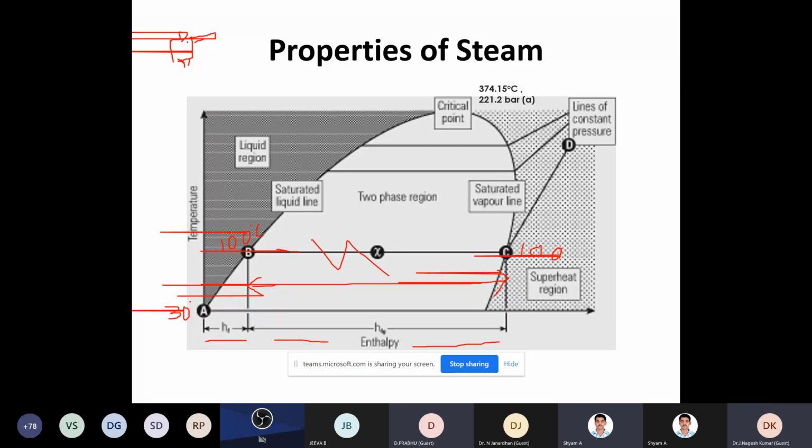So when does the rice cook? Now, when the whistles are coming, the pressure cooker has only acted like a steam generator. It's a boiler. It has generated the steam. After we switch off the stove, the steam inside the pressure cooker starts transferring the latent heat to the rice.